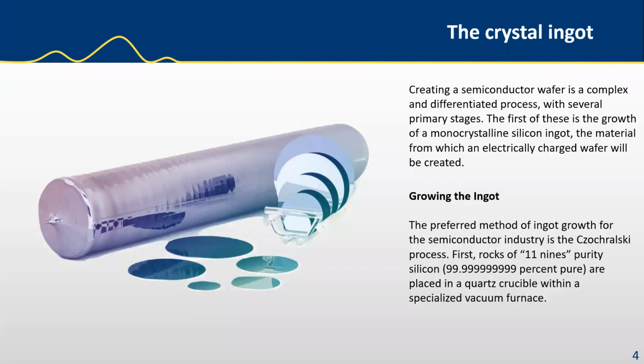The first step in semiconductor manufacturing begins with production of a wafer, a thin, round slice of a semiconductor material, usually silicon. In this process, purified polycrystalline silicon created from sand is heated to a molten liquid. A small piece of solid silicon, like a seed, is placed on the molten liquid. And as the seed is slowly pulled from the melt, the liquid cools to form a single crystal ingot. And we can see the ingot here in its completeness, the left image there, before the actual wafers are sliced into the wafers themselves.